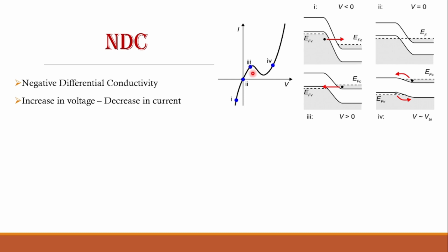Again next, if voltage goes on increasing, in that case tunneling is not possible because empty states are going on reducing, due to which we can observe reduction in the amount of current. Whereas even if the voltage is going on increasing, in that case the normal diffusion is going to take place because the potential barrier is very less.